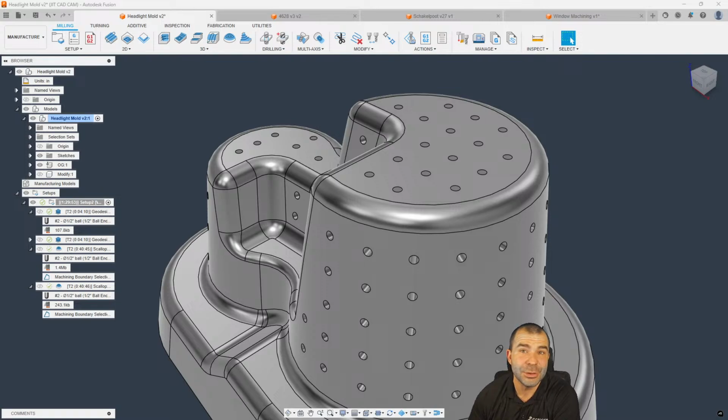Now, I prefer each one of my parts, maybe not on a setup one. I have a customer, maybe I'll see if he'll allow me to put it up, but me personally, if I'm patterning, if I'm using a tombstone and it's the same part 4 times around, things like that, my first setup, given that I'm usually using a stop and a simple square piece of material, I usually keep that with the concept that it's one work offset if it's easier for me to do. I have a lot of customers that run 100 parts off one work offset, and then I know people that run 100 work offsets, right?